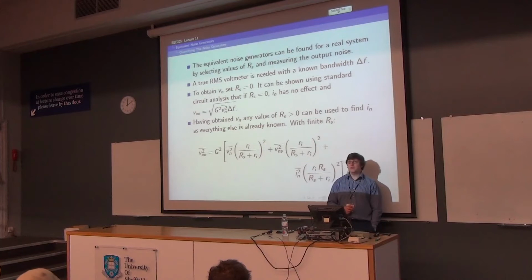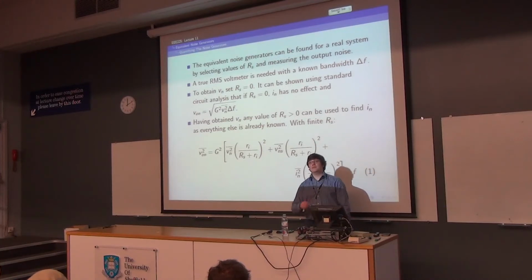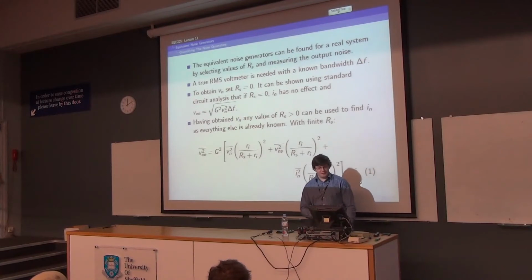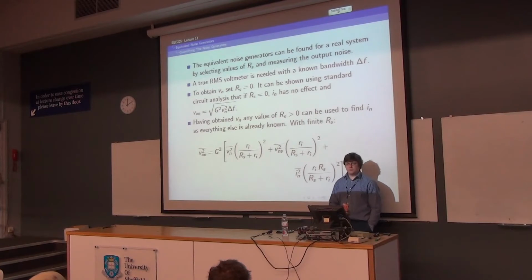The very best ones use your signal to heat up a resistor and then measure the amount of energy that's lost from the resistor. And that's because it's the heating power that's available, the equivalent heating power that's available. And then if you had one of those, it would be called a bolometer, not an RMS voltmeter. But mostly you can get an RMS voltmeter that's pretty good for a couple of £100 now.